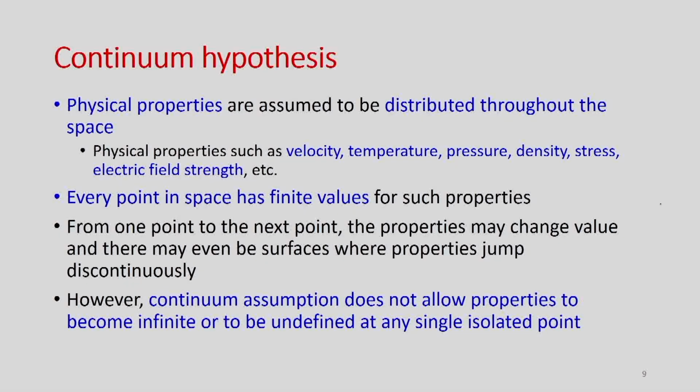Let us say you have a spherical particle in a surrounding fluid. The density of the spherical particle may be very different from the density of the surrounding fluid. At the interface, the density of the solid may be very high, and immediately the very first attached fluid layer has a density very different from the solid density.